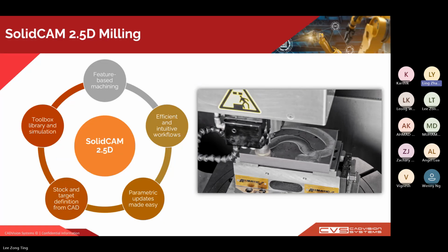So in SolidCAM, what we're trying to advocate to our customers is that for every operation that you wish to create in SolidCAM, it comes with a simple wizard that can guide you through creating operations like face milling, contouring, pocketing, drilling, engraving, and threading by first directing you to select the right geometry, then selecting the right tools, selecting the right strategies, and then you can simulate. So it's basically like a step-by-step guided wizard.